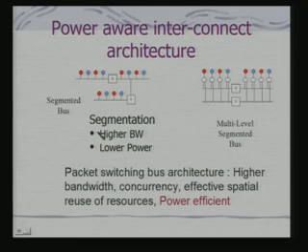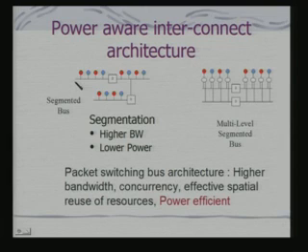In fact, we had discussed this already, you can have a segmented bus and a multi-level segmented bus. So, you have the bridges, and with that the components can be connected in either of the buses. So, you have a multi-level segmented bus with the bridge operating in between. Now, obviously, this multi-level segmented bus gives higher bandwidth, because the whole idea is that the high speed transfer takes place on a smaller bus where it is required, and the low speed devices are connected via the bridge. So, the effective transfer rate is more.